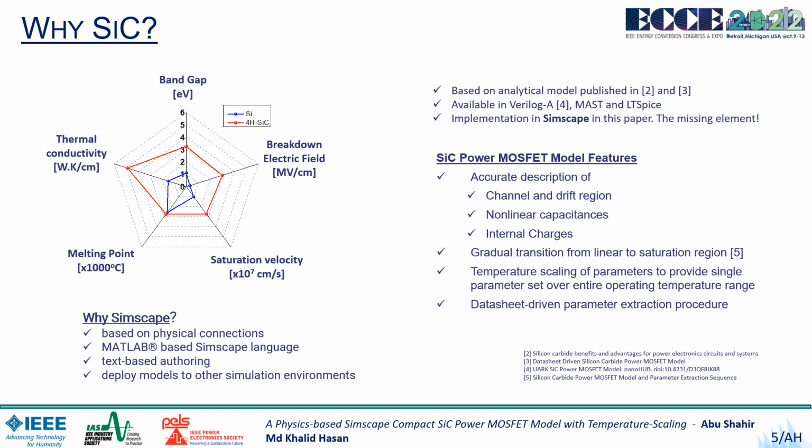Silicon carbide has gained popularity recently because of its superior device characteristics. A higher critical breakdown field means a voltage rating can be maintained while still reducing the thickness of the device. A wider band gap leads to lower leakage current at relatively high temperatures. A higher thermal conductivity supports a higher current density. Silicon carbide devices can operate at high frequencies because of higher saturation velocity.